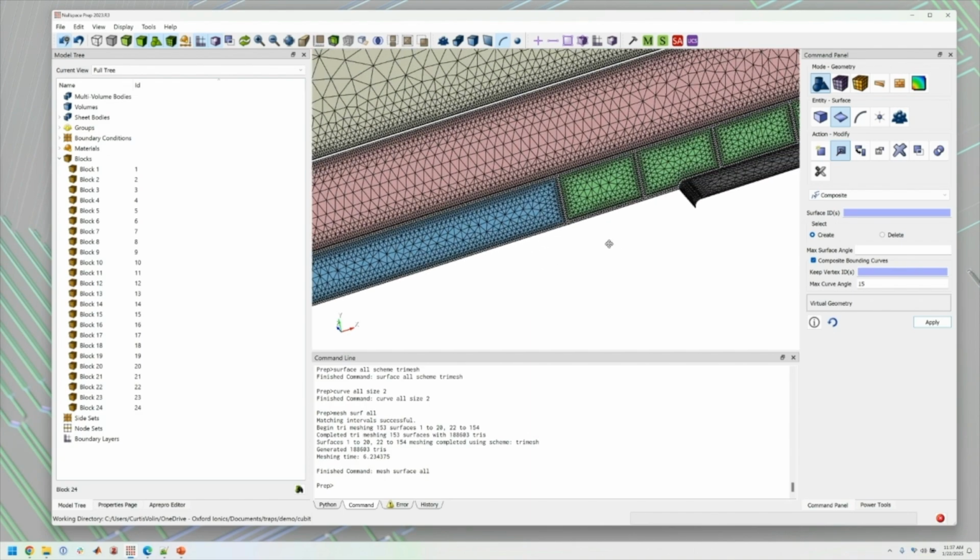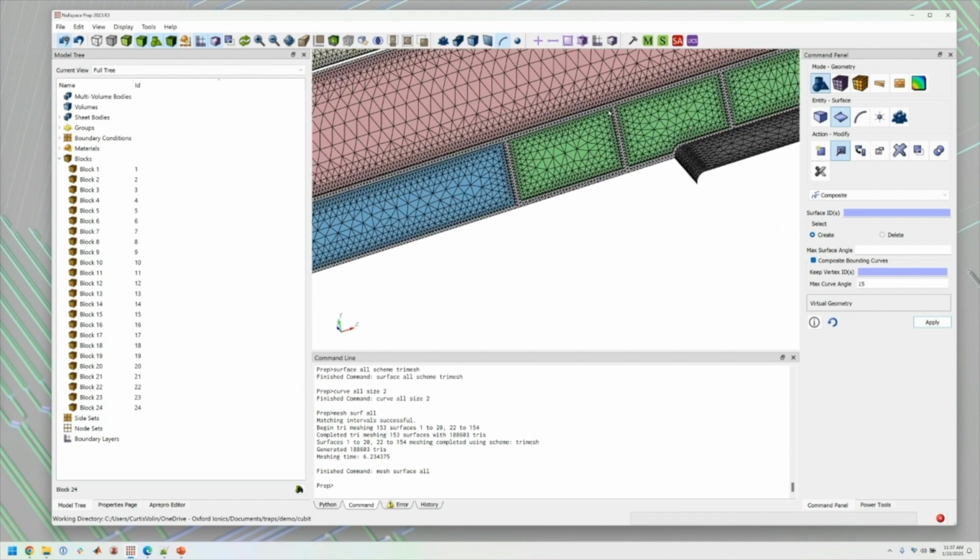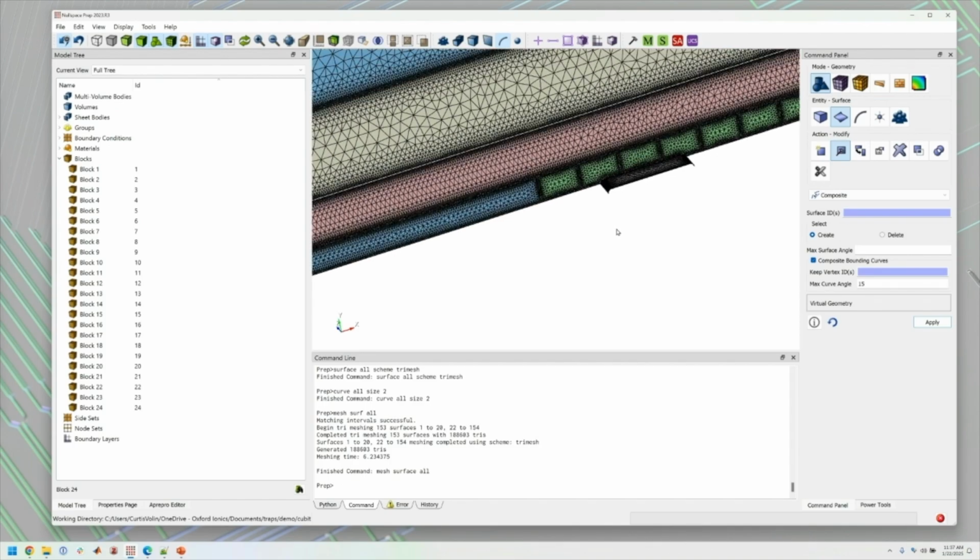When it does the charge solve, for every charge that's present over here in a triangle, it's going to make a virtual triangle over on the minus y plane that has the same charge. That's even symmetry, or it's going to make one that has the negative of that charge. That's odd symmetry. So we're going to run 2 simulations. The first one has the even symmetry, so that corresponds to having a volt on both this electrode and its mirror electrode. And we're going to run odd symmetry, which corresponds to having 1 volt on this electrode and minus 1 volt on the mirror electrode.